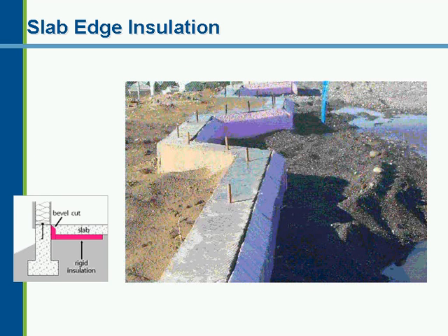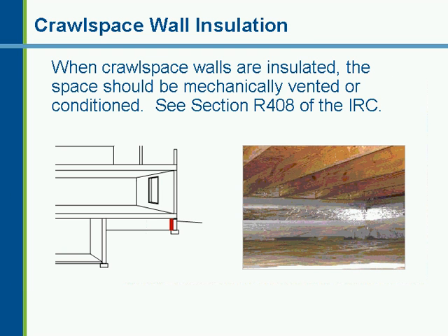The next graphic will show there is an allowance to cut the top of the insulation if you've insulated on the inside of the stem wall at a 45-degree angle. That makes it easier to attach nailing strips and such when you get the house completed.